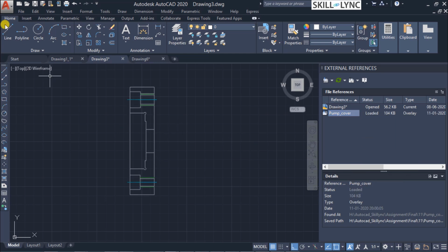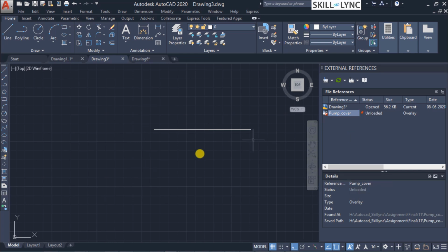let me say it. Suppose we are drawing a component, so that has to get reference from this point of dimension. So we have considered this component, and now I do not require to load this component each and every time, but still have to have this reference in the memory as in the drawing, so that I can know where this reference comes from. In those cases I can do the unload operation so that my AutoCAD drawing opens up much faster and also uses lower memory, so that I'm optimizing it here. But the pointer to the reference will always remain here. So by this we can understand where it is used and why.